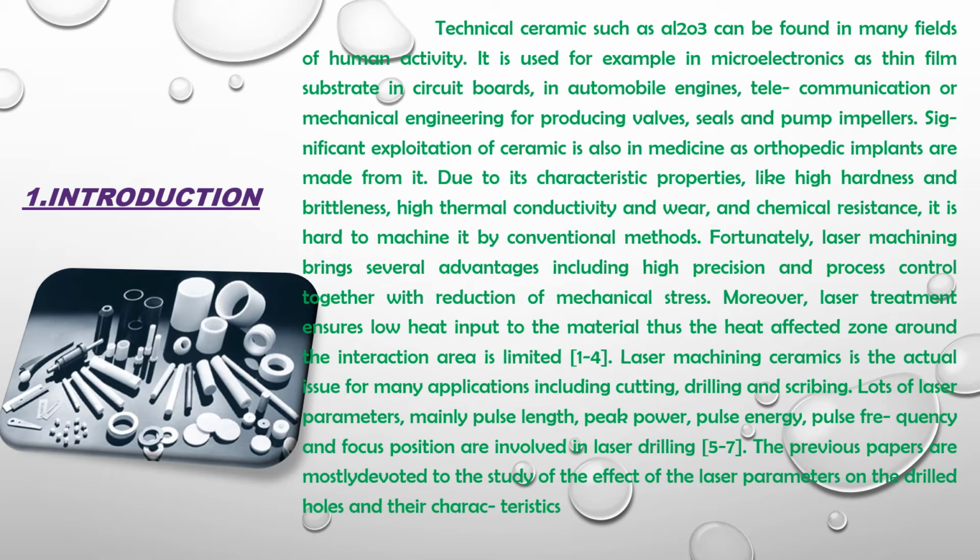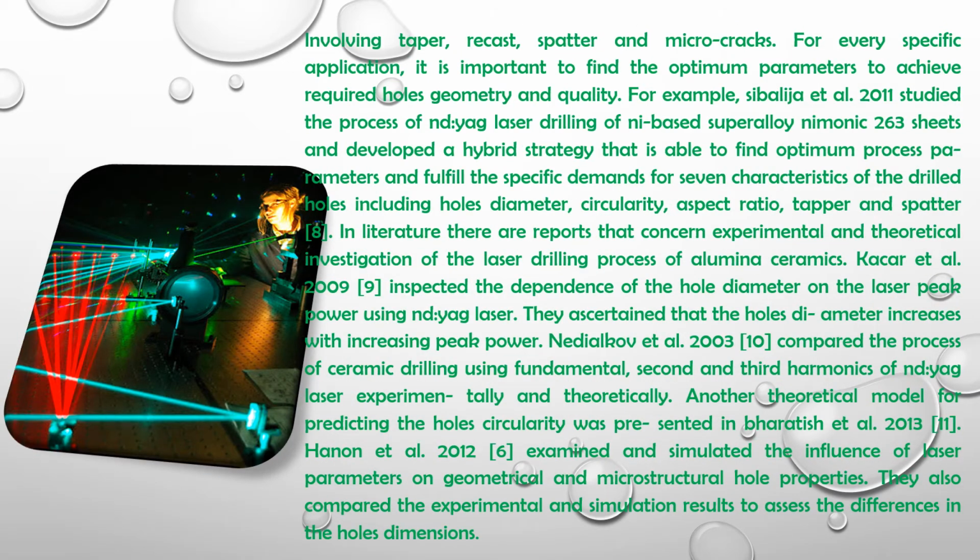Lots of laser parameters, mainly pulse length, peak power, pulse energy, pulse frequency, and focus position, are involved in laser drilling. The previous papers are mostly devoted to the study of the effect of laser parameters on the drilled holes and their characteristics, involving taper, recast, spatter, and microcracks. For every specific application, it's important to find the optimum parameters to achieve required hole geometry and quality. For example, Ciganovic et al.